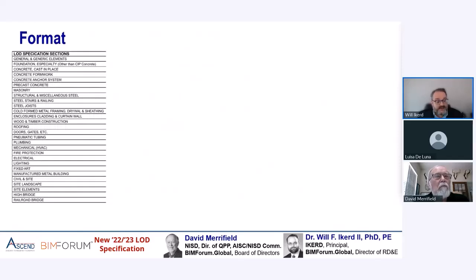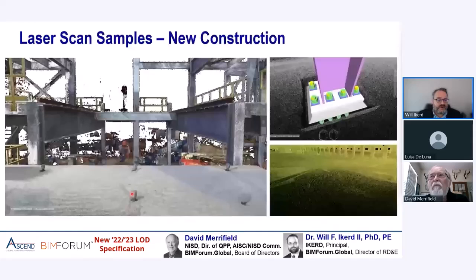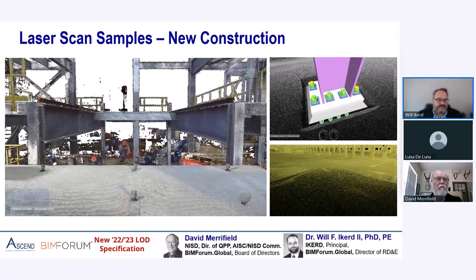These anchor rods you see here in this image are 3-inch diameter. This is on top of a 20-foot by 20-foot pedestal that's 13 feet tall, solid concrete. This is what a massive incinerator sits on. These are approximately 40-inch deep girders with train rail on top, and the train rail is what the door of this incinerator rolls back on when they go to open it. Then there's a lift that brings things up and puts things into the incinerator, and downstream it has about a 160-foot tall stack. These are very large projects, so if you get an anchor rod off, it's a showstopper. And you don't just field bend a 3-inch diameter anchor rod.